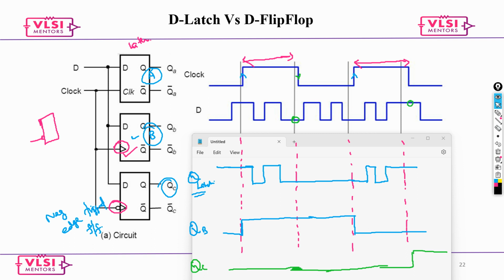On a simple note, a latch is basically level sensitive. If it is positive, then during the positive level it is transparent. You can use that word, transparent, as simple as that. And when it comes to flip flops, it is edge triggered, and whatever the value at the time of the edge, rising edge or falling edge, that value would be considered.